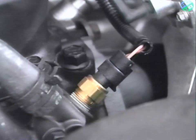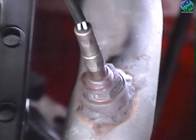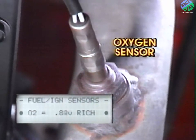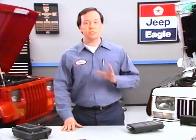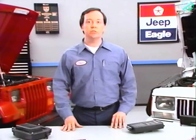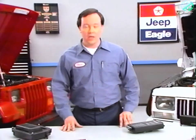If there is a problem with the circuit, the controller senses whether the circuit is shorted or grounded. The engine controller can determine if the oxygen sensor is switching between rich and lean once closed loop has begun. Now that's a brief look at just some of the circuits the engine controller can detect faults in. Now let's look at some of the systems the engine controller cannot detect faults in, the non-monitored circuits.